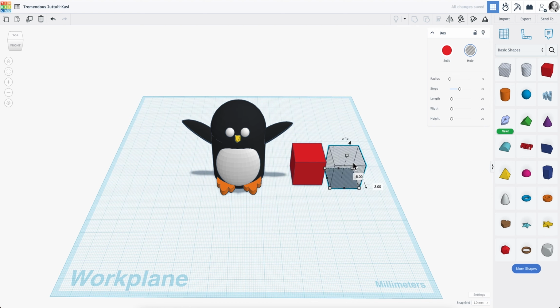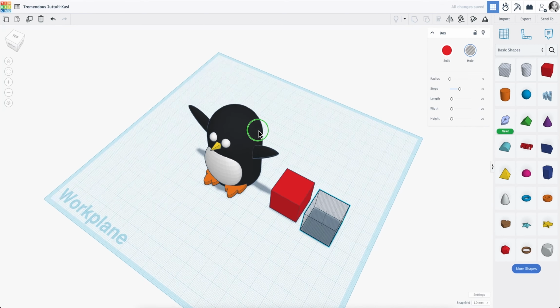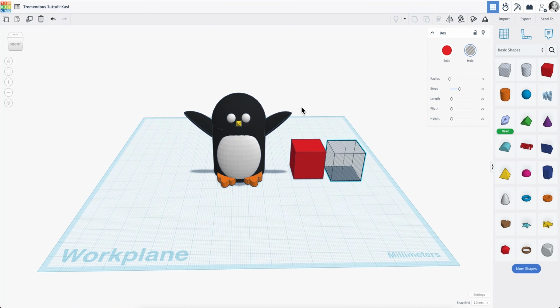Now, remember one thing, if you have a moving part within your characters or within your object, you need to print those separately. So if you have hinges or something that moves, at this point, this process is not going to work perfectly. So any moving parts, you should add them separately, away from your character. In this case, you can print them and just attach them to your product. And your product in this case will have a moving part.